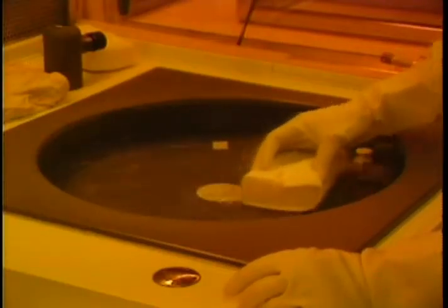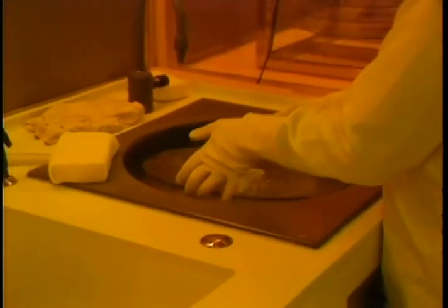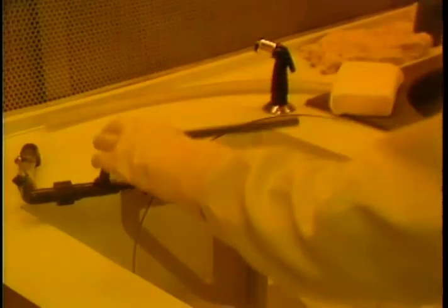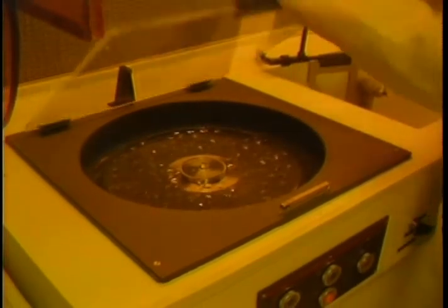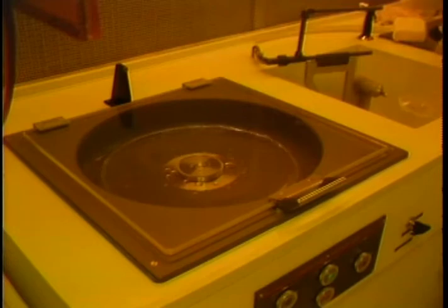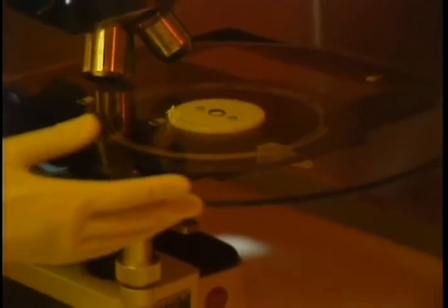The first task is preparation of the master. A raw glass substrate, highly polished on one side, is prepared. Each is washed with a special cleaning cloth, rinsed for 4 minutes in deionized water, then it is spun dry. Next, a dark field inspection is made, the first of many quality checks that the master undergoes. Here, the operator sees a solid black surface. Any particle of dust appears as a white speck. The master is stored face down in a protective can between steps.